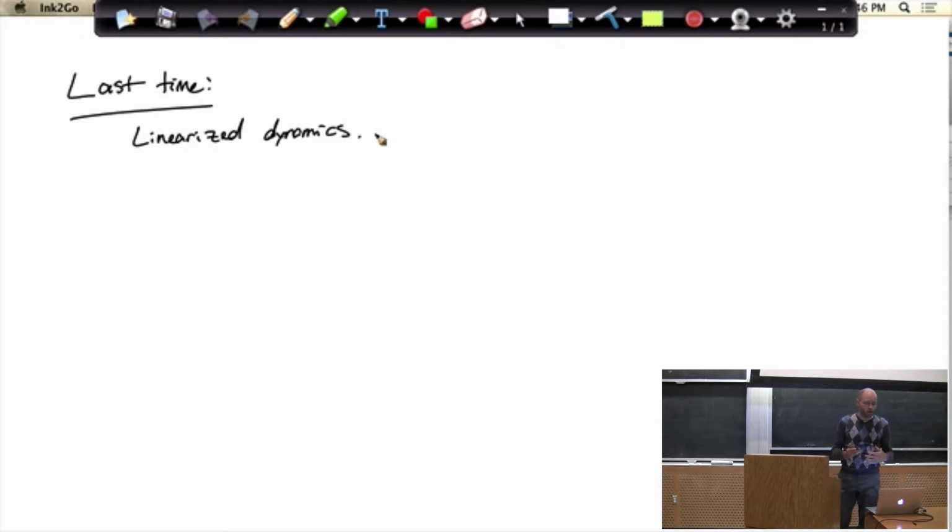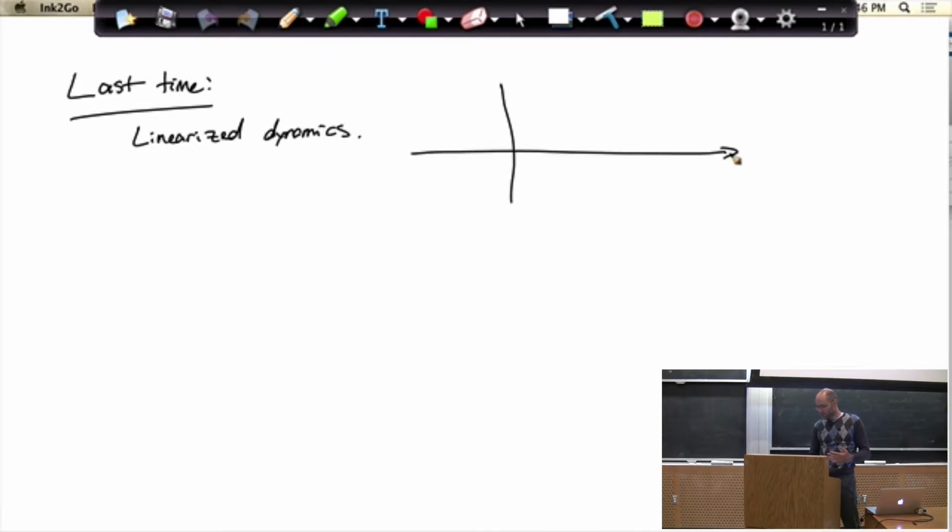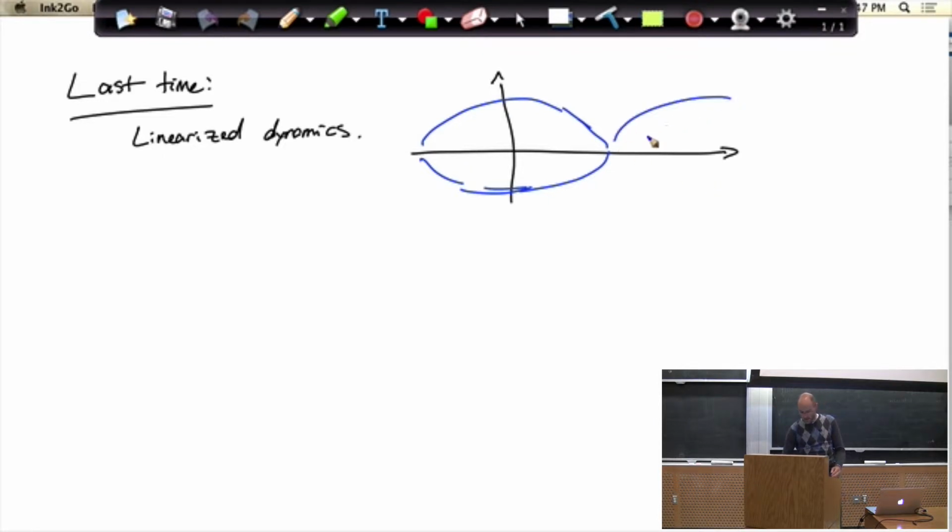Around some operating points. So for balancing the cart pole or the acrobot around the top, we were able to come up with pretty good approximations. If you remember, I tried to argue that the pendulum dynamics, which in this characteristic form looks very, very nonlinear, we were actually getting a pretty good approximation of with our linear approximation, which captured the nonlinear dynamics in some vicinity, right?